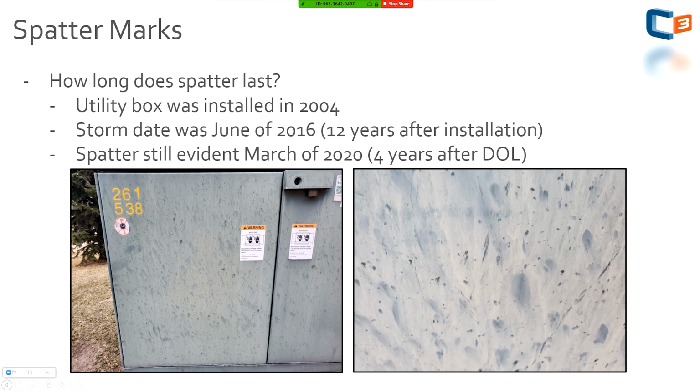So if you're looking at a single ply roof system like EPDM that's dark in color, that'll oxidize and you'll find that it gets chalky. If you kneel down on old EPDM, your knees will be black and you'll probably ruin your pants. So a lot of that is just oxidation of something with a chemical makeup or a painted surface.